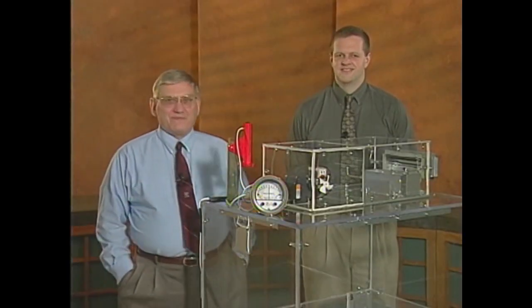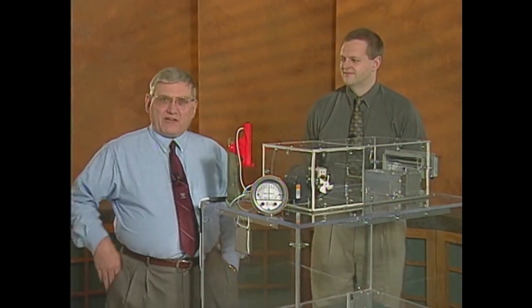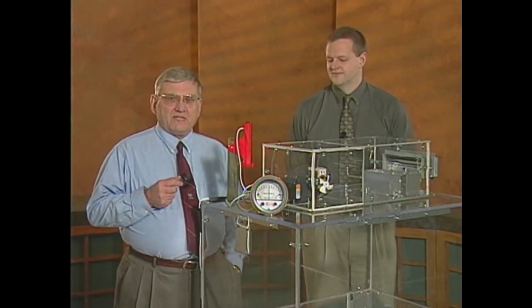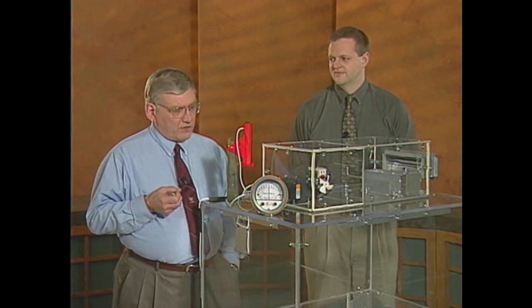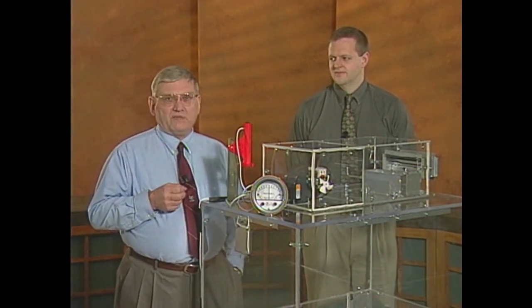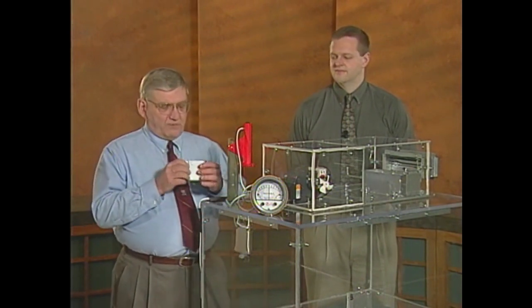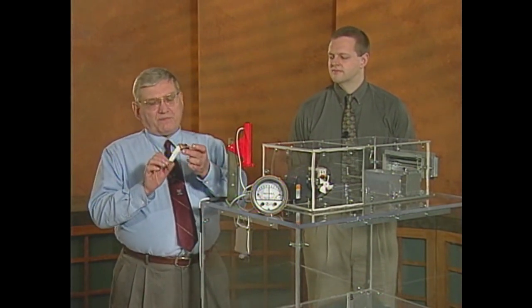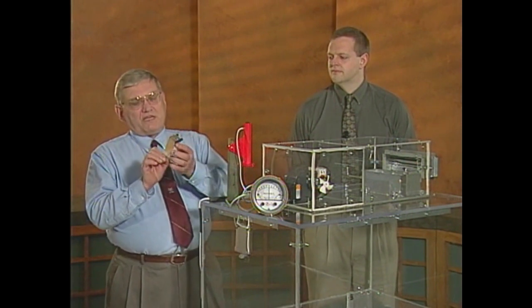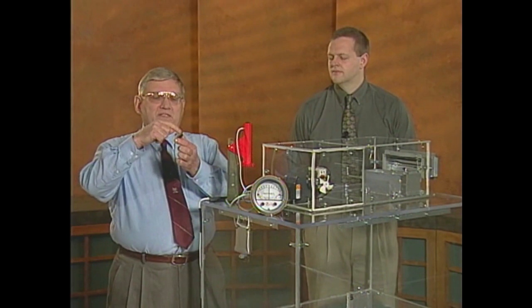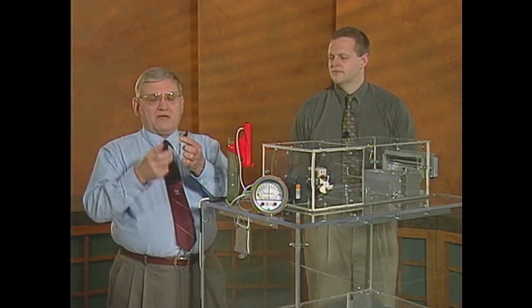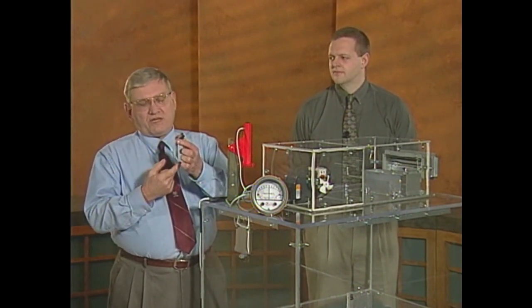Now let's watch Art and John again as they play with the building models. Thanks, Dennis. Local barometric relief dampers can be demonstrated with our model. Barometric dampers allow positive air pressure to leave the building through an alternate route than the front door of the building. Here's a real but very small barometric damper. Notice the shape. It's hinged at this point in the middle, so it's counterbalanced. The extra metal on the top offsets much of the weight below.